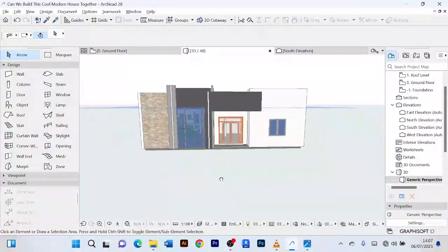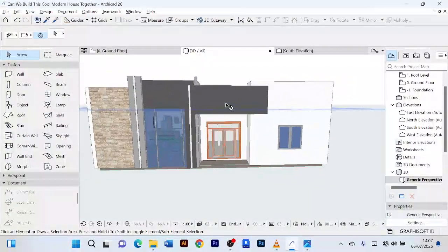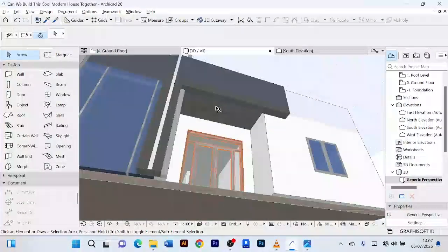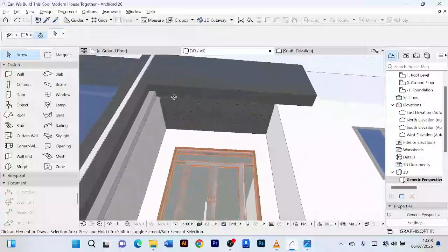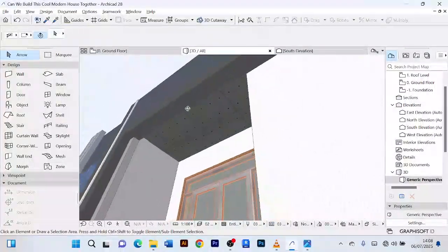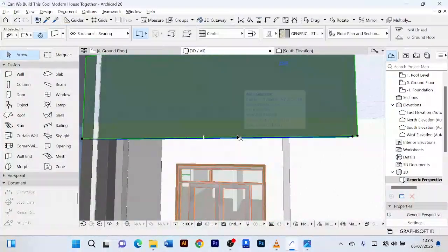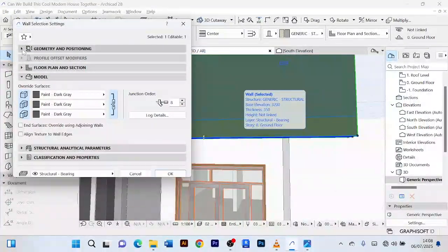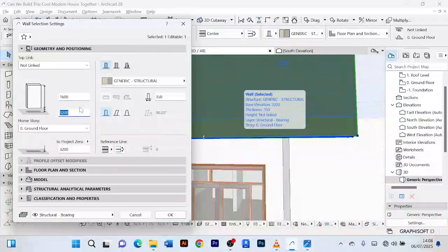cancel. So you see that we are doing well with our facading, and I believe you are learning a lot of things. So let's see this part. I want this one to go to this. I want it to sit perfectly at 3 point. We shall Control T. We come to geometry. From here, instead of 3.2, I'll do 3.3.